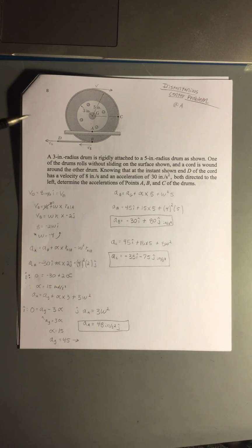And so by looking, we know that the velocity of D here will have to equal the velocity of B because they're connected, and the acceleration of D on this rope is the acceleration in the tangential direction of B, and then B will also have a normal component towards the center of the circle here that we'll have to account for.